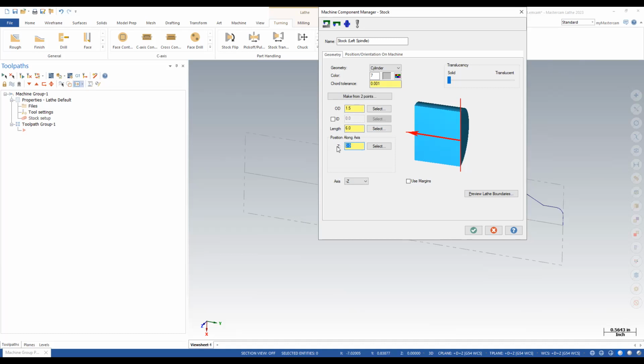So now, what's the position along the Z-axis? It should not be 0. Is it negative though? Positive. You know why? We touch all the tools off on the stock. What do we do at G54? We shift it in 25 thou to Z0. So this right here would be the opposite value of what you put into G54. Because it pushes the stock out, we push the tools in with G54. Making sense? Yeah, I think that's what we put in our G54 when we set it up.